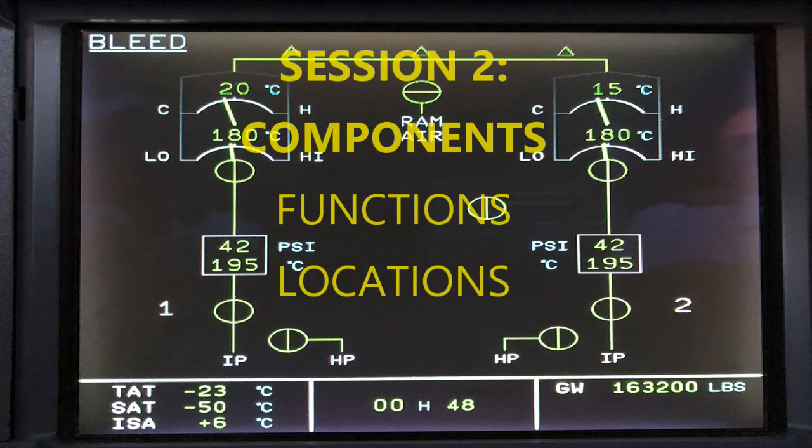We have this one, and it's also monitoring the pressure of the engine bleed air. So here's a similar design, transducer as far as that goes, but you have that one as well. It's just regulating the pressure. Okay, the other one was talking about a transferred pressure between two valves. Here, this is just monitoring the pressure of the engine bleed air.